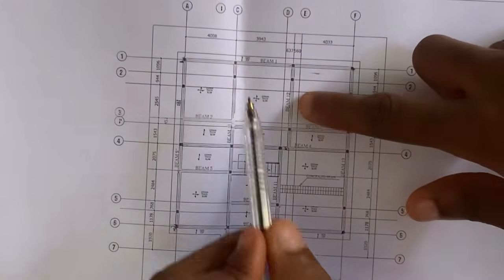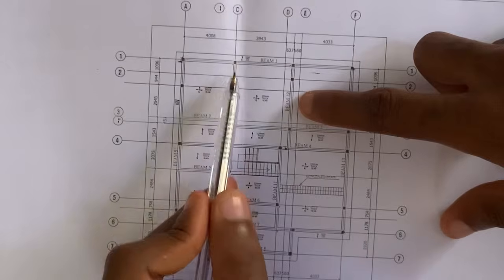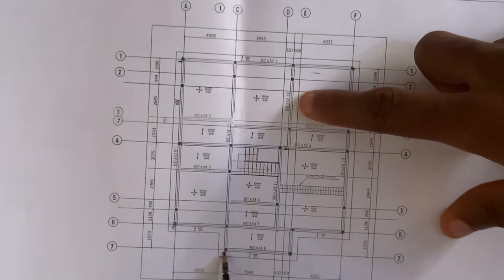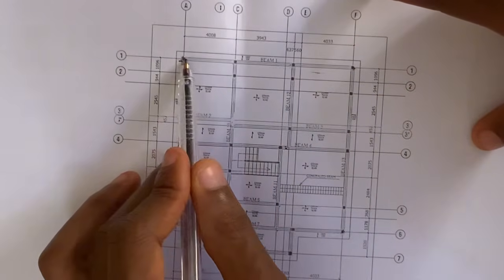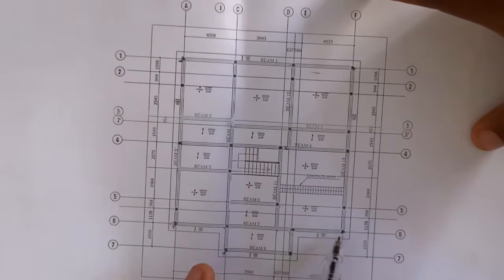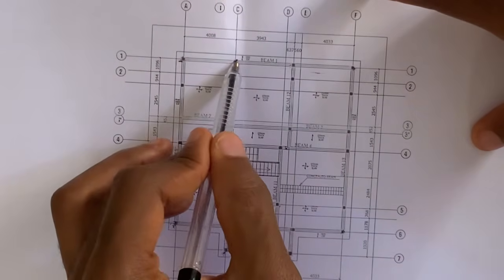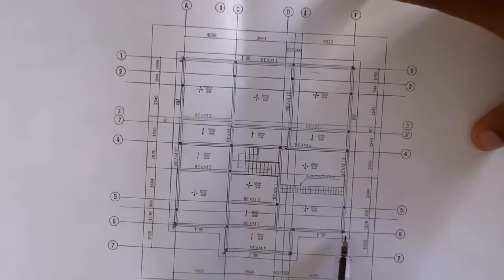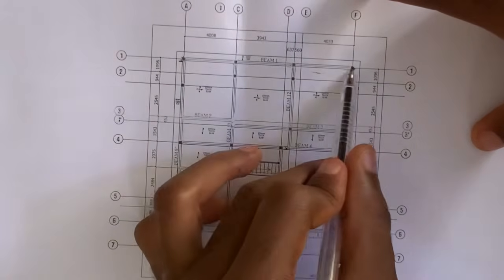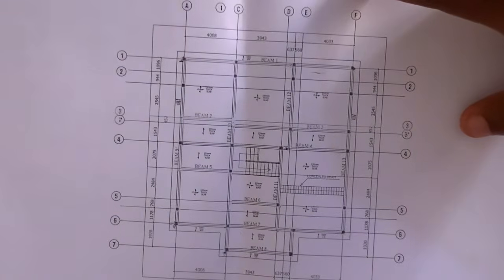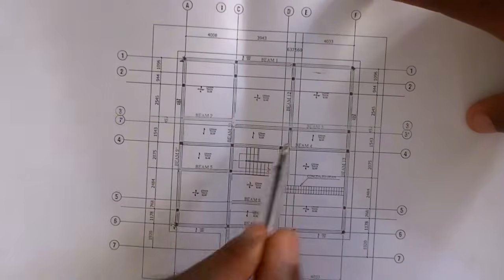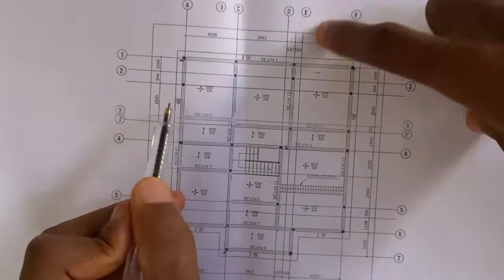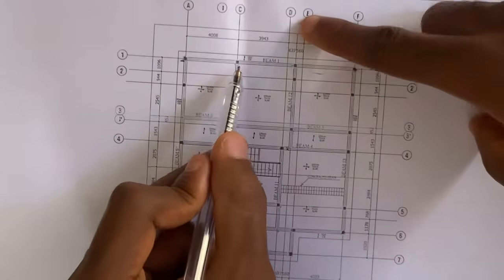So the next beam we're going to be looking at is what? Beam 10. And it told us that beam 10 is running from this point down to this point here. But remember that we've already measured for this beam here. So it means that this beam 10 has been cut by what? Beam 7 and beam 1, which has already been measured. So how do we now measure for beam 10 when we've already cut it by measuring beam 7 and beam 1 separately? So now what we can do now is this.